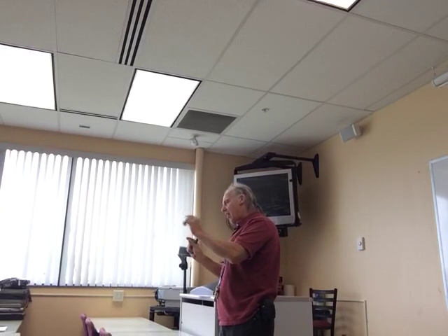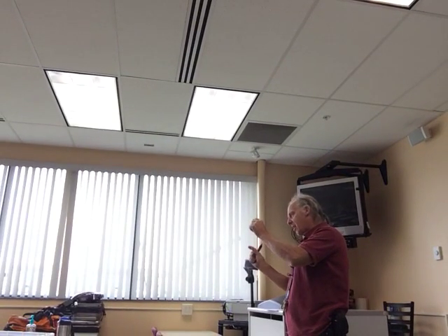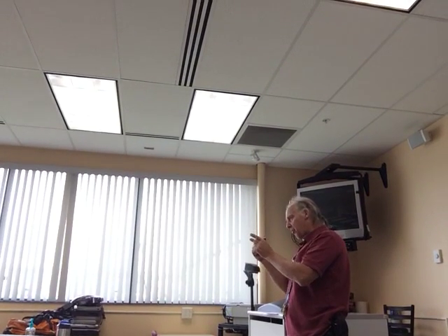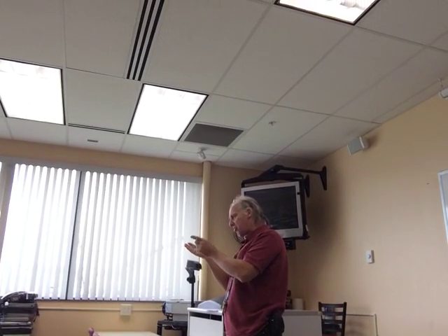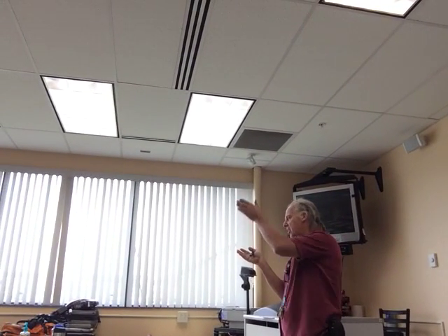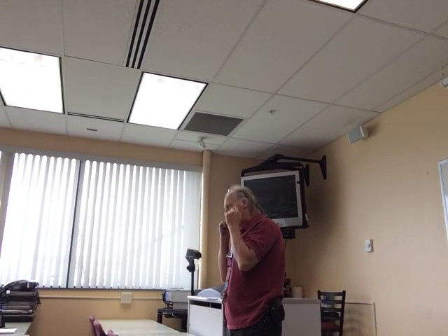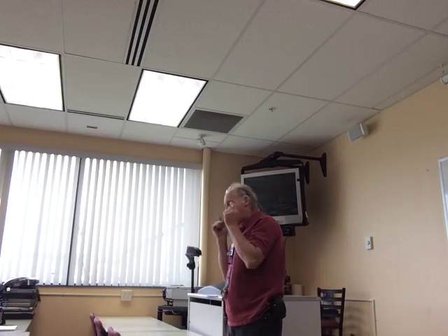When I pull that off, what happens over here? That voltage is going to change right away, isn't it? Because I'm going to unload the circuit. That little parallel circuit goes away, and it's just a single resistor in the series circuit, right? Okay, so you got to take that into account. You know, I always remember that's what I did, okay? All right.